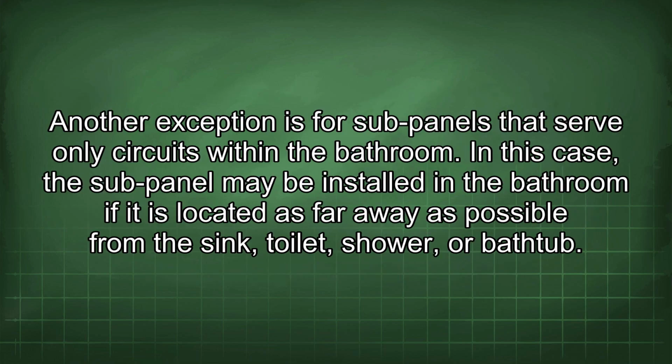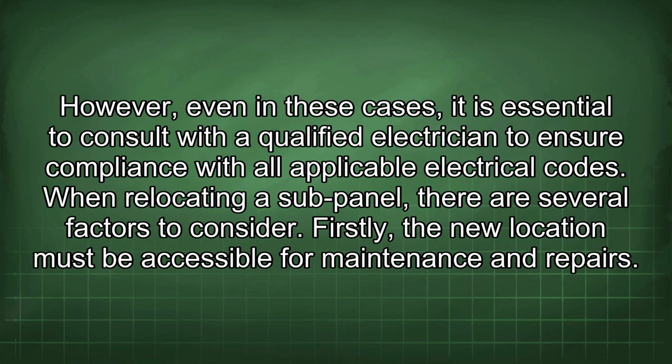Another exception is for sub-panels that serve only circuits within the bathroom. In this case, the sub-panel may be installed in the bathroom if it is located as far away as possible from the sink, toilet, shower, or bathtub. However, even in these cases, it is essential to consult with a qualified electrician to ensure compliance with all applicable electrical codes. When relocating a sub-panel, there are several factors to consider.